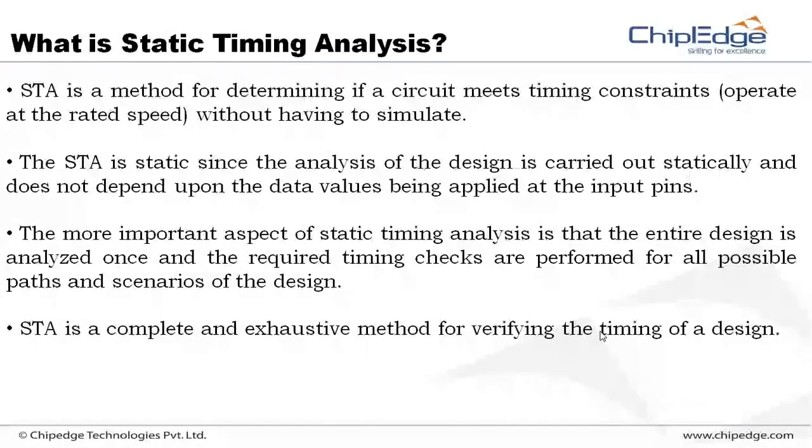So, see, you might have written Verilog code and you might have written the test benches. While writing the test benches, you might have given some input vectors, right? So for a full adder, if you want to check, you might have given 0, 0, 0, 0, 0, 1, 0, 0, 1, 0. Like that, inputs you might have given and tested whether it works properly as a full adder or not. But here, we don't do it. No input values will be given, hence the name static. We don't give any input values, but we will see whether it works or not.